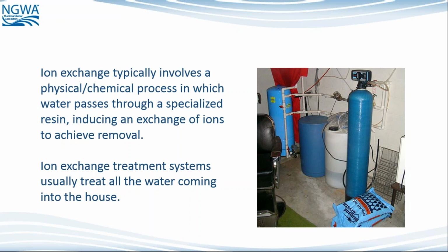So you have a lot of little balls of media in a vessel, but they have charges on them, either positive or negative charges. And as the water flows through this media bed, there's an exchange of an ion off of the media and a fluoride ion onto the media, removing the fluoride from the flowing water. So we call that ion exchange.